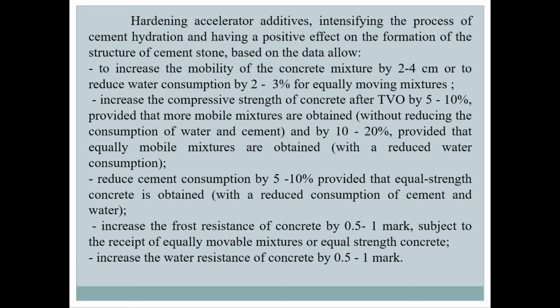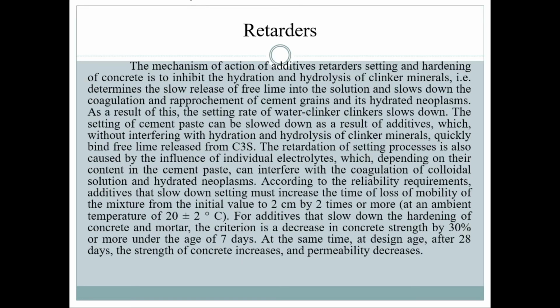Increase the frost resistance of concrete by 0.5 to 1 mark, subject to obtaining equally mobile mixtures or equal strength concrete. Increase the water resistance of concrete by 0.5 to 1 mark. Retarders. Two mechanisms of action of additives that retard setting and hardening of concrete: to inhibit the hydration and hydrolysis